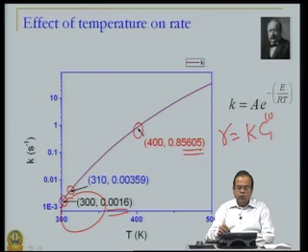However, even though rate and concentration are linear as it appears in this expression, the rate constant K is dependent on temperature in a non-linear manner, such as shown over here. Now, as we will see later on, in a reactor, concentrations and temperatures do not change independent of each other, at least if you are talking about, let us say, an adiabatic reactor. So, if we are talking about an adiabatic reactor and, let us say, an exothermic reaction, then concentrations and temperature are related